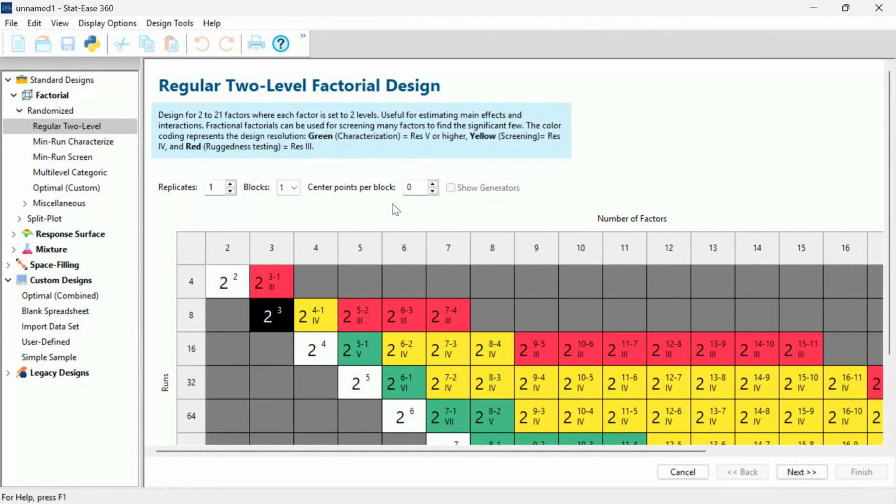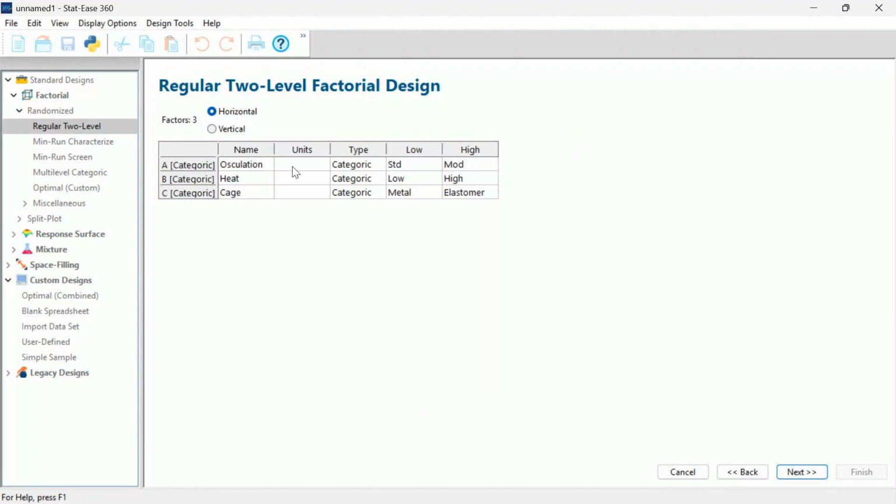Normally, if we're working with numeric factors, which might have been the heat treatment, we're not told exactly what that was because of confidentiality, we would want to do a middle heat treatment, not just a low and a high. Obviously, for a categoric factor like metal versus plastic, there's no middle of that. And so, this design was what they ran and it worked. So, hooray, let's not criticize it.